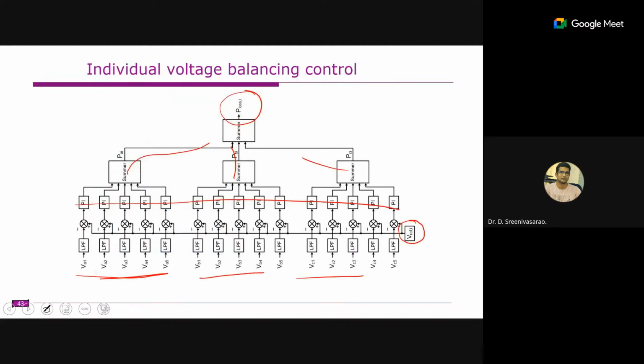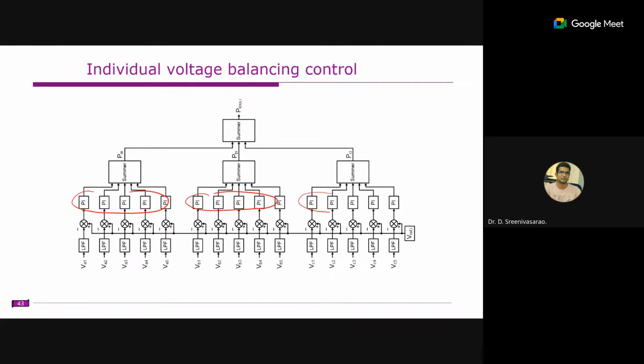Right. And another thing is that the tuning of these PI controllers is usually simple. We are using a PWM method like the phase shift PWM technique, right? So we can easily tune the capacitor voltages. If you have properly tuned the capacitor voltages, it will be good. I think my results are there.